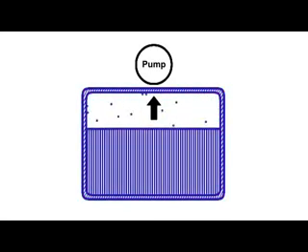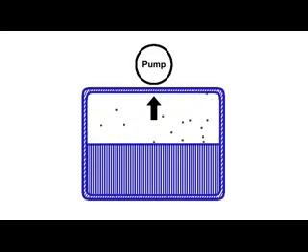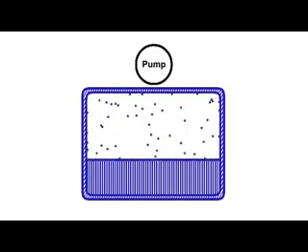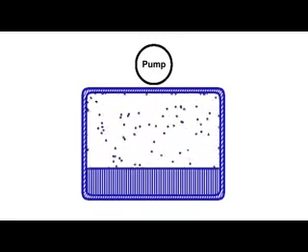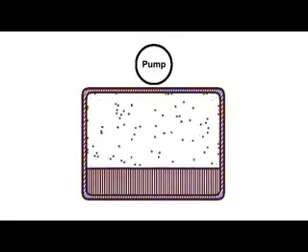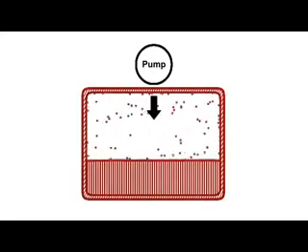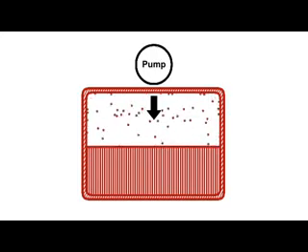You've likely heard that water boils at some lower temperature in the high altitude environment of Denver, which is another way of saying low air pressure environment. Well, it does. It boils there at about 195 degrees Fahrenheit rather than 212. And the opposite holds. Instead of 212, water boils in a pressure cooker at about 230 degrees Fahrenheit.